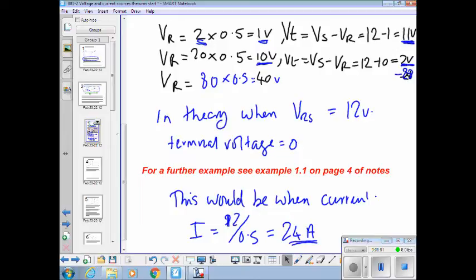But without zero terminal voltage, you won't get there. That'll melt everything in most sources before you ever got anywhere near that. That's only a model, remember. The idea is we can model a real voltage source by considering its internal resistance. And you've already come across it in your diagrams for your attenuators, remember? When we did that on Multisim, we had to put our actual source at twice the voltage we wanted because you're losing half of it across the 600 ohm internal resistance.